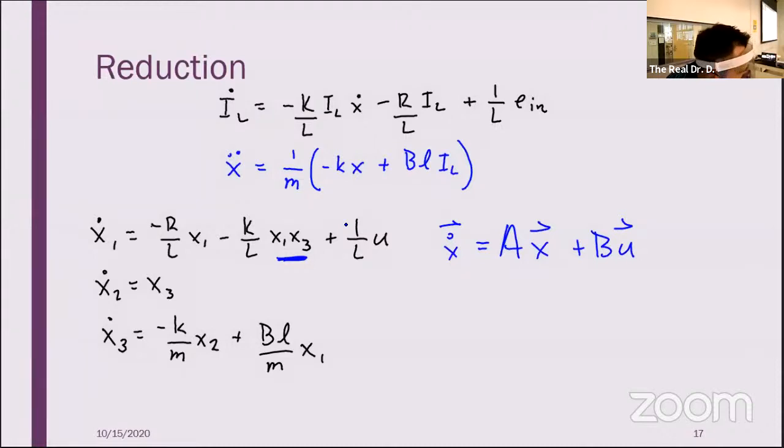But typically when we're dealing with state space, we deal with systems as a whole, not as parts. State space is really nice because it tells us everything about the entire system as a whole when we solve it. And because it's a matrix equation, when we write our output equations we can define multiple outputs and solve for all of them at once. But the very specific caveat is that you need a linear system in order to use state space.